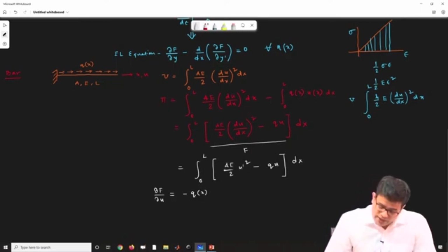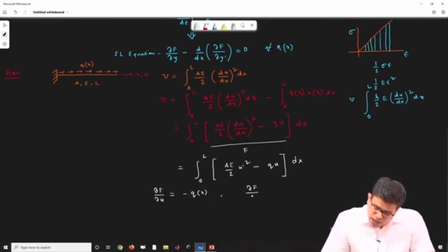So assuming that this is f, the second term, del f by del u prime, is this. So this is nothing but AE u prime, right? So now if I write it, AE du by dx.